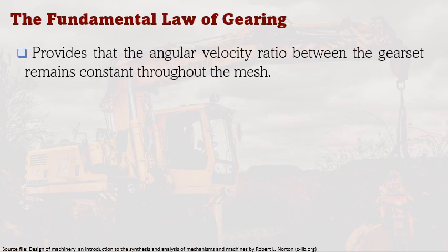The fundamental law of gearing provides that the angular velocity ratio between the gear set remains constant throughout the mesh, which is a very important parameter because, especially for very good timing, for example, this will require that the angular velocity ratio should be constant throughout the mesh.